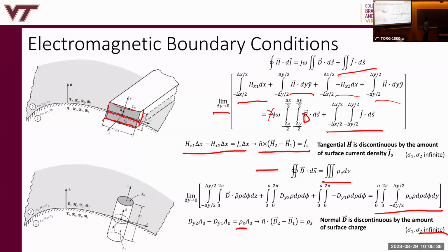So what we're going to find later is there's a thing called skin effect, where charge can exist inside. That complicates things. But here we're talking about a hard boundary between infinite conductivity, where we definitely have infinitesimal layers of current and charge, and finite conductivity, where we don't. In practice, copper is assumed to have this kind of infinite conductivity, and we would use these boundary conditions.